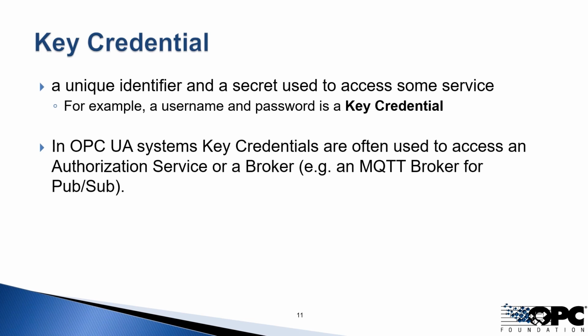So in PubSub, where we use MQTT as the middleware for the publishing, typically the broker service itself is secured, and it will require some key credential to be passed to it in order to use it, and therefore the OPC publisher or subscriber would need to know that key credential. So by centralizing the management of the key credentials, again, I can update them, revise them, change them and present them in a centralized manner.